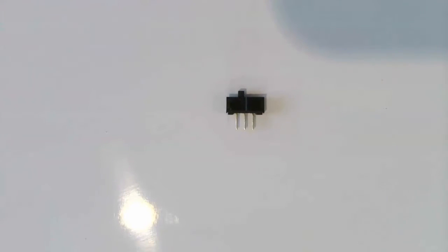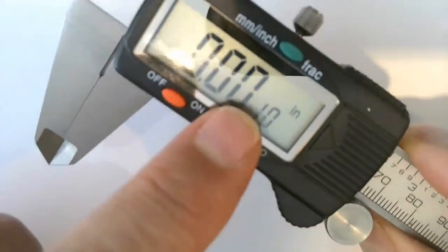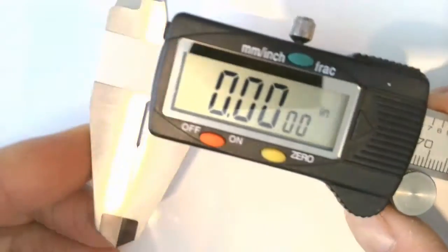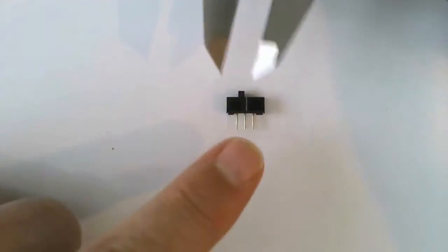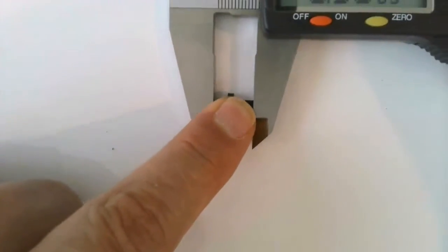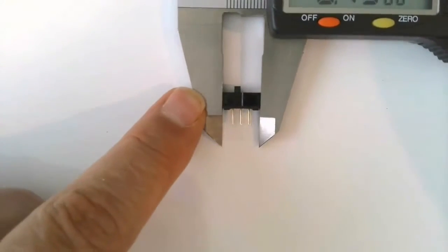Now you could start with a symbol or you could start with the package. It doesn't really matter. But in this case I'm going to just start with the package. So I'm going to make some dimensional measurements here. I'm going to take my calipers, zero it out, make sure the jaws are closed and that they're clean. I'm going to wipe those down and make sure that it's zeroed out. And I'm going to measure first of all the outside dimension here. And I make a measurement of